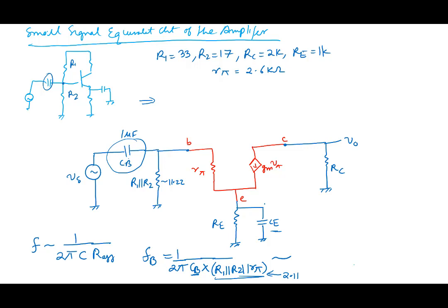How much did you say? 75? All right, I think that's what I'm getting, 75 or so, 75 hertz. Maybe there are slight deviations. So that's due to FB. If CB was the capacitor causing the 3 dB frequency, the 3 dB frequency would have been 75 hertz. Now let's test our other assumption.